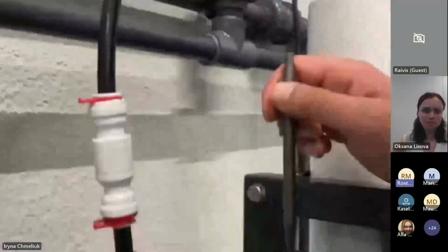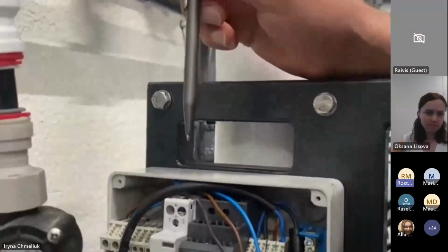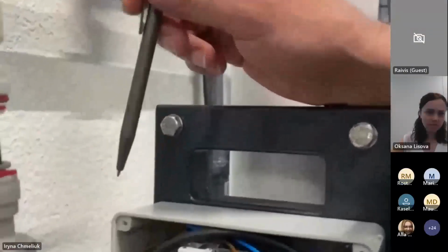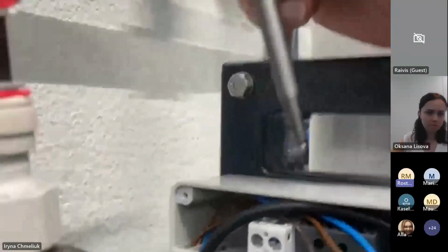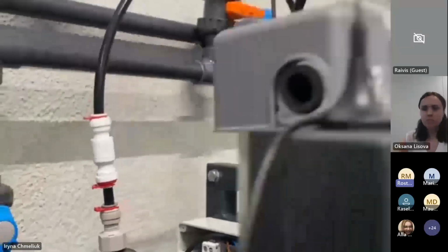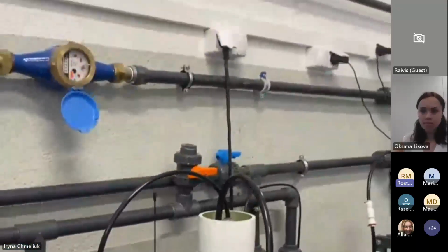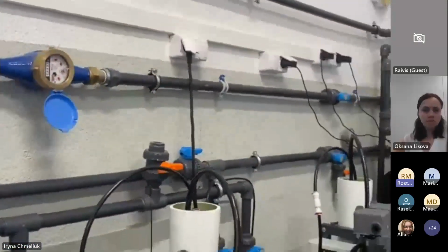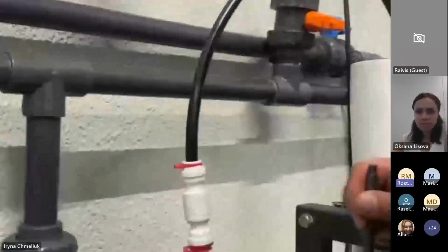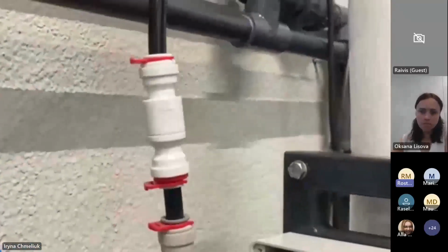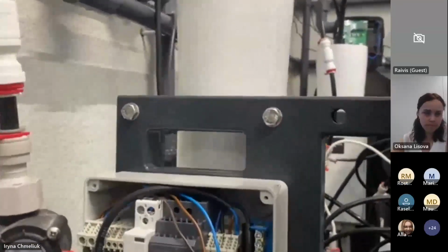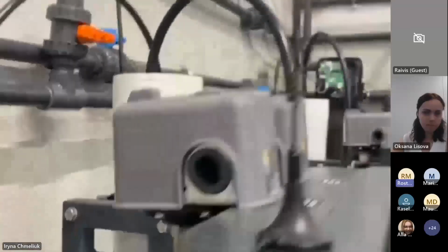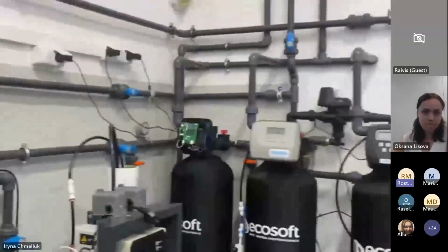open the control panel here. The microswitch is connected to the contacts. I think this is the contacts. I would need to tell you exactly, but these are shown in the manual. I would ask Alexei. Alexei has already answered: we have the contacts 11 and 12 on the contactors. They are here, where you connect the microswitch. So this is the answer to the question of the microswitch.